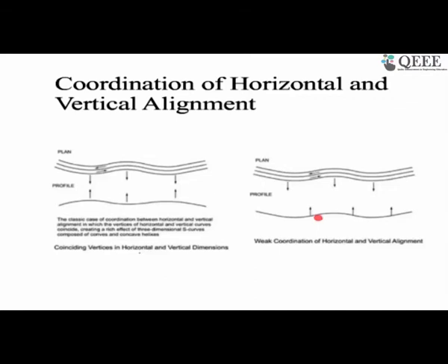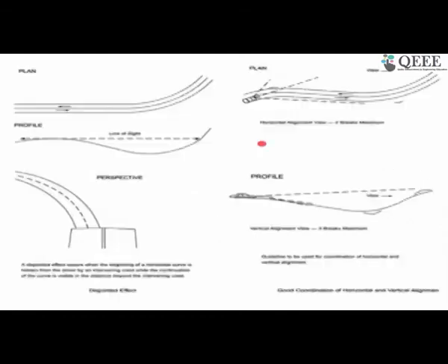We should remember that we should provide the horizontal curvature right on the top, not on the other side of the vertical curve, or right before the summit curve, not on the other side. So this is what we are coordinating. If we move it to the other side, it is going to be difficult. So you have to consider the roadway which is going from one direction to the other. You have to consider both sides of traffic.